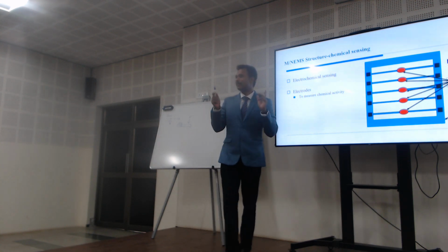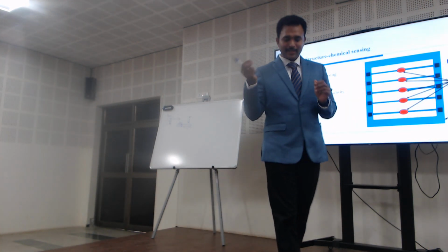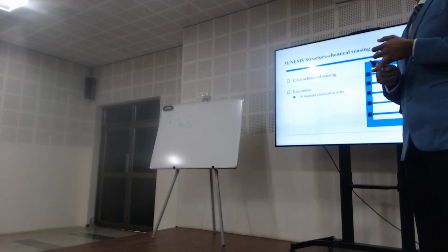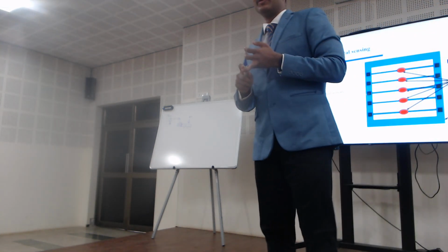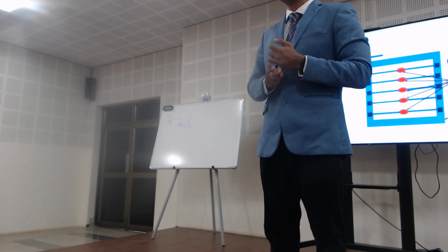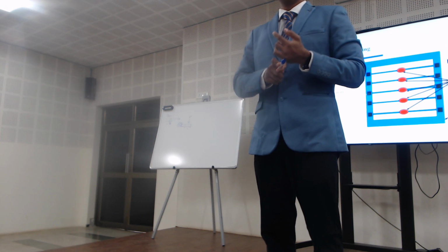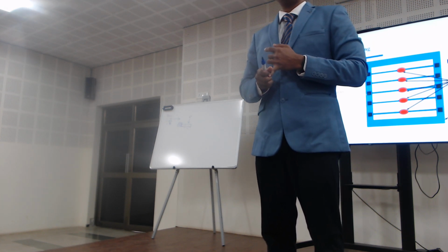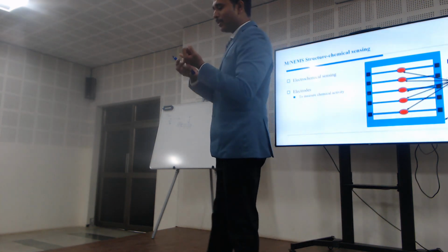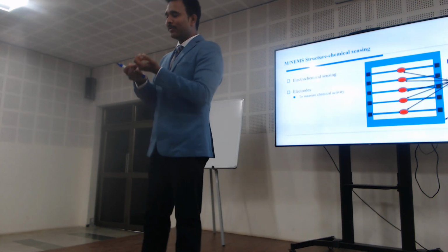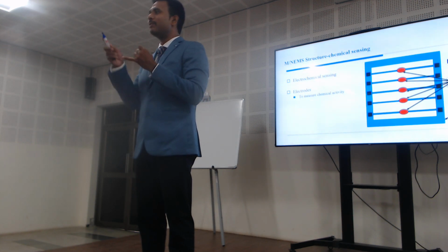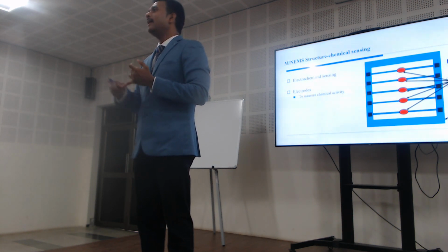Like that we have two types of sensors: one is the movable type of sensor, and the second is the rigid kind. In the mechanical field, the accelerometer and gyroscope all come under movable sensors. To design a movable sensor, we have to mainly focus on the suspension beam structure, whether it should be one directional, two directional, or three directional.